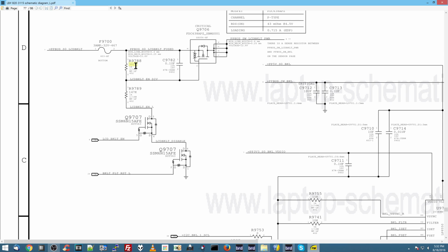So remember, this resistor is going to be what limits the current. So the current being limited over here is what's going to allow this resistor to then drop the voltage. However, if there's no current limiting, if the entire ability of the circuit to provide voltage is present over here, it's not going to do much. It's not going to actually drop anything. Remember, a voltage divider requires the top resistor and the bottom resistor. If we take away the top resistor and just replace it with a wire, it's not going to drop anything. So if this is shorted or this is shorted, we get nowhere.